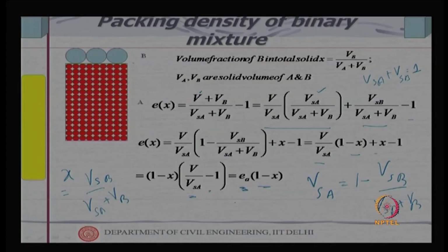Let me repeat this process. What I have done is add some coarse aggregate into the fine system. If I add just a few of them and push a little from the top, a small amount, it is unlikely to disturb the packing characteristics of the fine aggregate too much, because the fine aggregate quantity is very large.